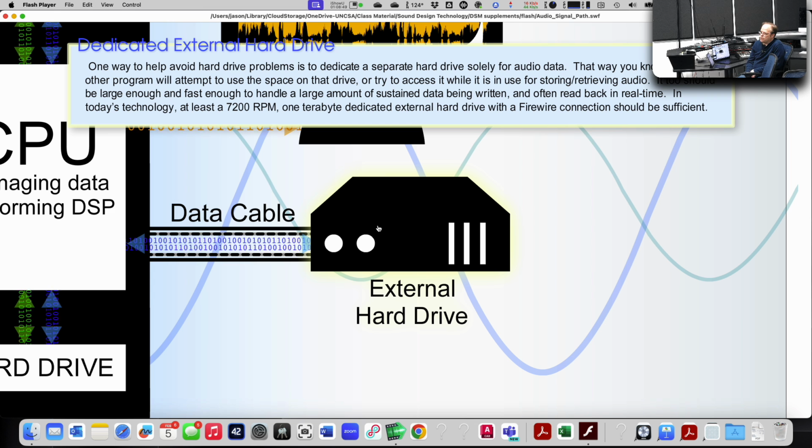you're looking at a USB 3 connection, which will be at best 5 gigabits per second. USB 3, USB 3.1 can do up to 5 gigabits per second. And that's a pretty big difference. A lot of the drives that look like they're USB-C are actually just USB 3 with a USB-C connector on it. They look like USB-C, but they're actually running a USB 3 chip, which means you're maxed at 5 gigabits per second. So if you're buying a drive, look at that spec.